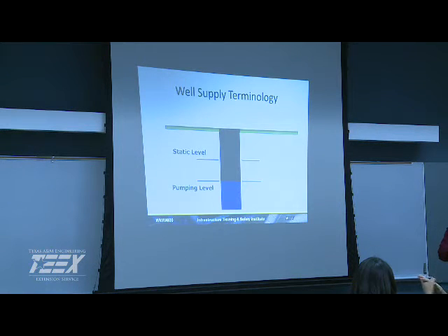Yeah. What you would need to do is look at, there should be drilling records on it, and you can look at the aquifer type, and if it's an artesian aquifer, then you're probably flowing. But you've got to look at your hydraulic grade. Are you at the bottom of a hill, at the top of a hill? Where are you at? It's pretty flat, but what do you have around you? Are there any hills around you? Yeah. Not that high.